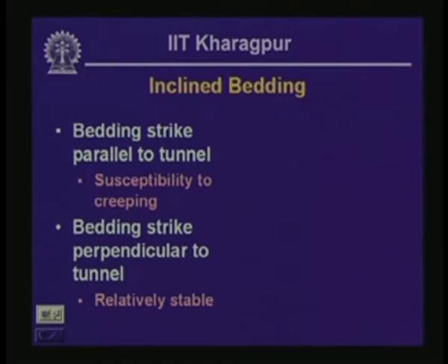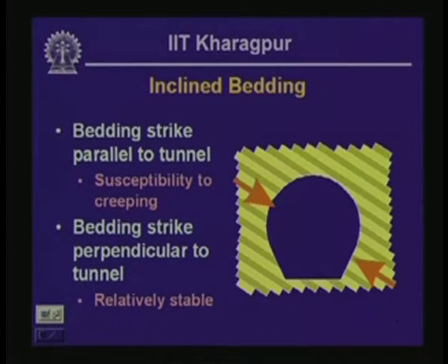In order to illustrate this, I am going to show another animation. Now let us say we have got a tunnel constructed through a bedrock which is inclined, for which the bedding planes are inclined in that manner, and let us consider in this case the major principal stress has the directions indicated by orange arrows.